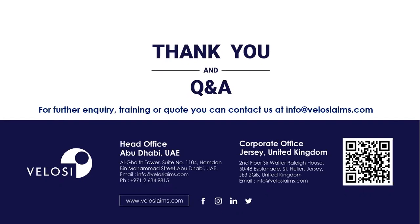Now, coming back to normal fire and gas, the generally acceptable SIL level is 2. For 3, it would be very difficult to achieve because when you test any number of, let's say, oxidation type detectors or infrared type detectors or heat detectors, normally their failure rate is 1 out of 100. And if you want to go to level 3, you should go to 1 out of 1,000. And you may not be able to maintain that SIL level.